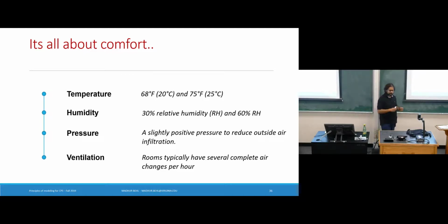One key aspect of HVAC control or operation is to maintain some positive pressure in the building. People don't know this, but buildings are kind of like aircraft. They are cans which are positive pressure. Not to the same level as a spacecraft or an aircraft, of course, because we are already at atmospheric pressure. But we need a positive pressure because we don't want dirty air with particulates entering the building. So if the building is at a slightly positive pressure, it's trying to push air out, so that outside air cannot just come inside the building on its own.